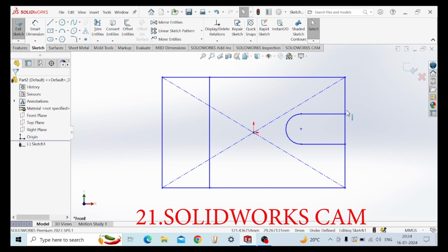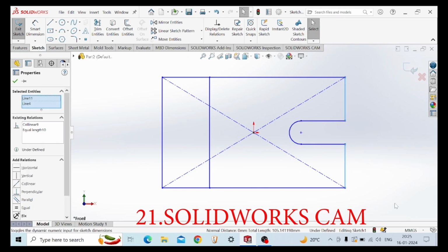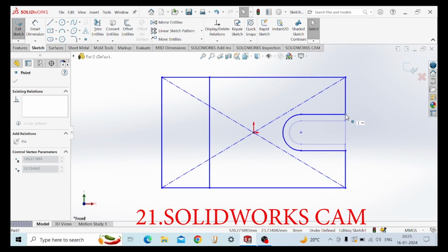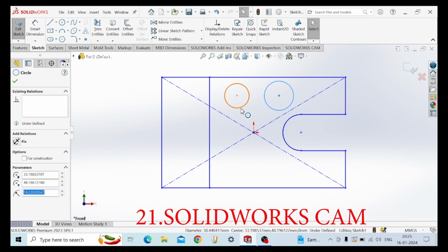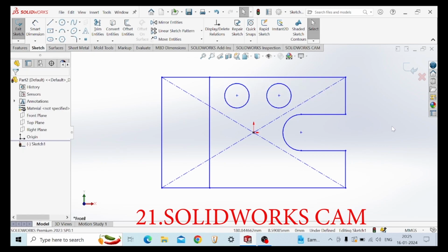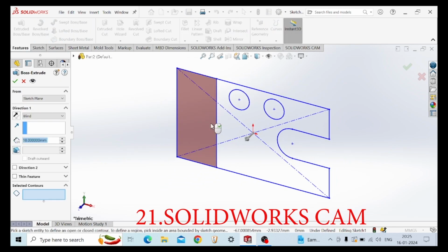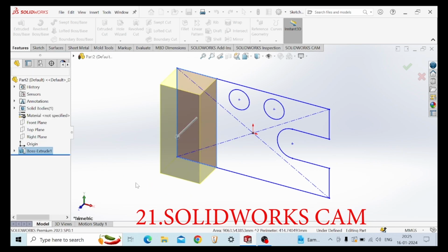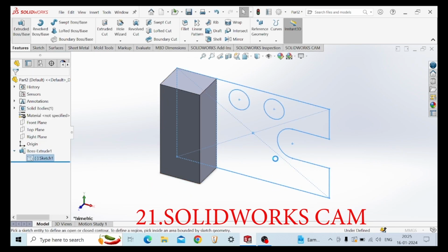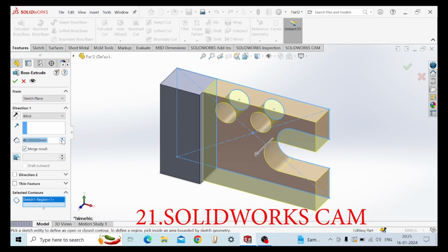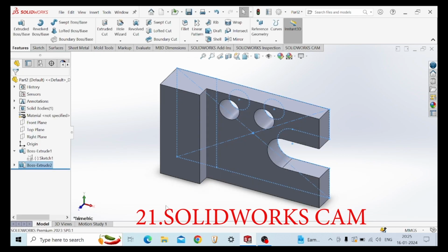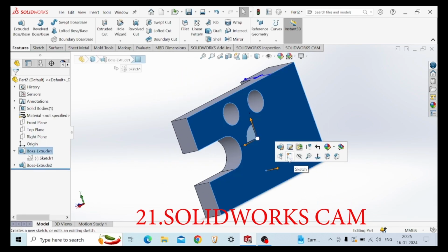Now SolidWorks CAM is extremely important and is very complicated. So here I'm going to just give you an overview. Now the resolution of the video is a little less, so bear with that. So first of all, I'm drawing this geometry on which I'm going to perform the CAM. We are also going to understand the cutting path generation, CL file generation, and the G and M code generation, which we are ultimately going to input into the CNC machine, okay, which will give us the part.